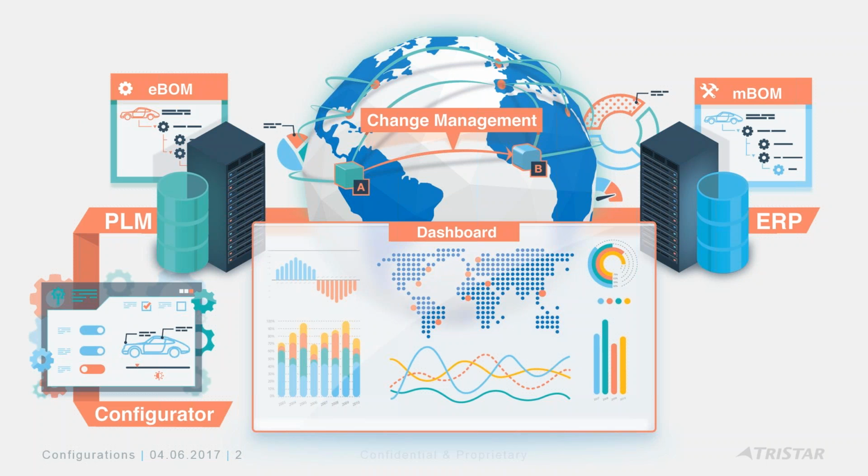We have been passing bill of materials information between Windchill and ERP using web services, typically through an enterprise change management process, such that when you release a product or a bill of materials, through the workflow we can call a series of web services and push that information over to ERP.